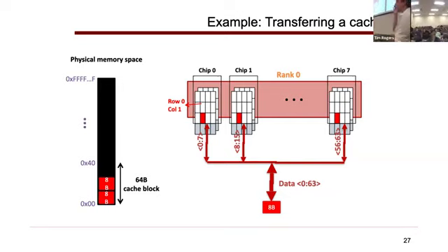Okay. Because when you put it in the cache and you set the valid bit to 1 and you put the tag in there, that means it's good. That means that whole line is good. So you need to have all the data. Okay. So there's going to be some buffering mechanisms in here to sort of keep this stuff around. And yes, you could implement it in the cache, but now you're sort of punting some of the complexity of that buffering down to the cache, and then it makes it harder to hook it up to another memory system. So usually this just happens in the memory controller. Okay, other questions?